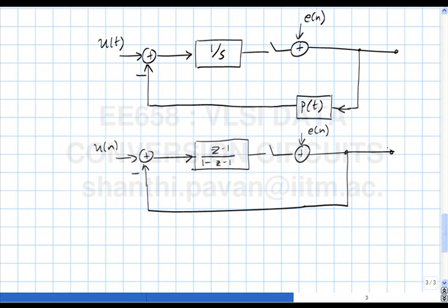Alright. So if I want to have the same NTF, correct? What do you think I should do? How do you think I will be able to? 1 by 1 plus P of S by S must map to 1. Okay. So in other words, there are many ways of doing it. One way is to make sure that the loop gain of both the loops is the same.